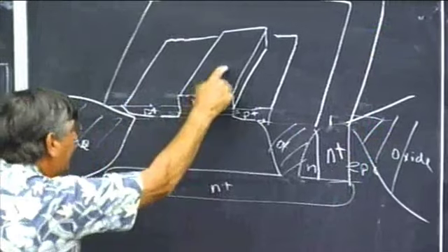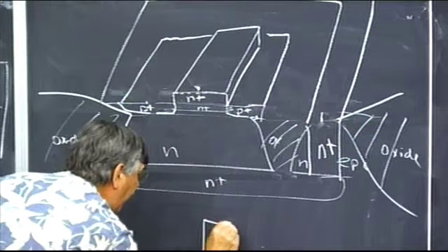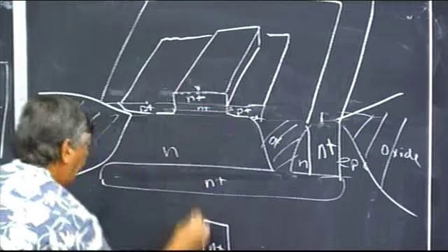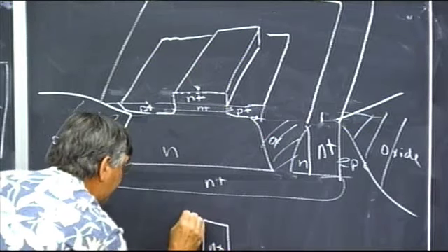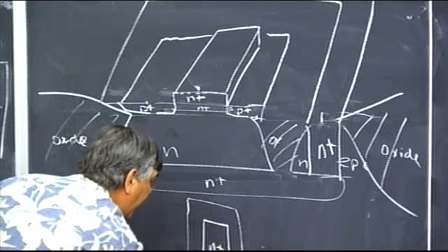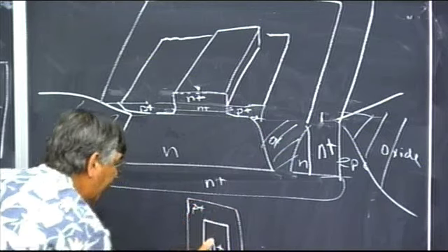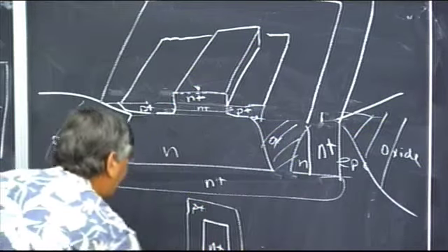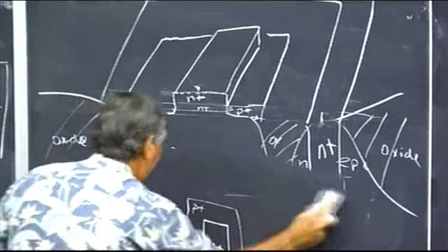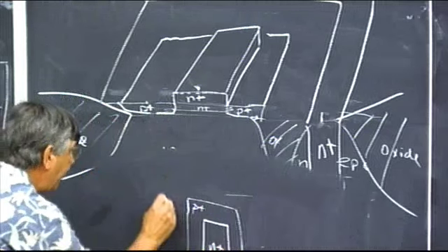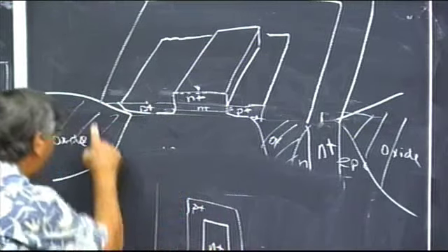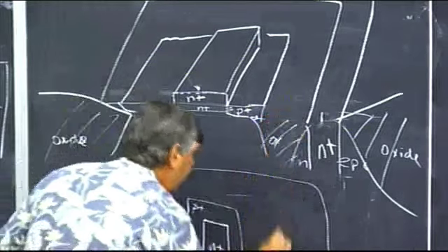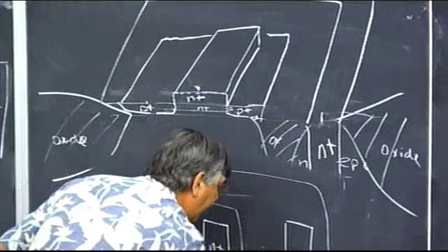So if we look at it from the top, we're likely to see an N+ emitter. We're likely to see base stripes on either side, maybe going all the way around. So this is P+, but there's P- actually underneath this guy. And then, I've got to erase some of this. I'm sorry. I didn't leave myself enough room again. But then completely surrounding all of that is the isolation region. And somewhere in that is an N+ contact for the collector.